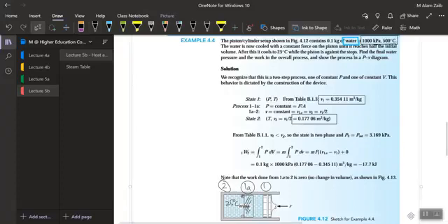Now, for 0.17706 cubic meter, we will be checking in a steam table again, and obviously we will be looking at the pressure, which is actually the same pressure. The piston is cooled at a constant force, so P1 would be equal to P1A. So the pressure which was initial is now the same pressure as well. So at 1 megapascal, again we would be looking at the volume, 0.17706.